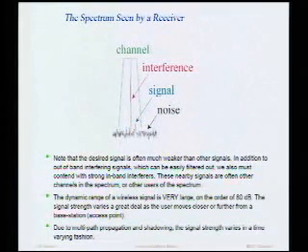Now you might say, well, where did this interference come from? Just suppress that interference. Actually, that interference is someone else communicating over a channel right next to your channel. Or it could be some other source of interference that you have no control over. So you can't simply gain up your own signal, because then you'd also gain up the interferer, and eventually the interferer would make your system clip.